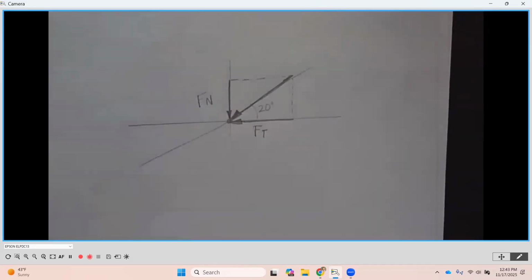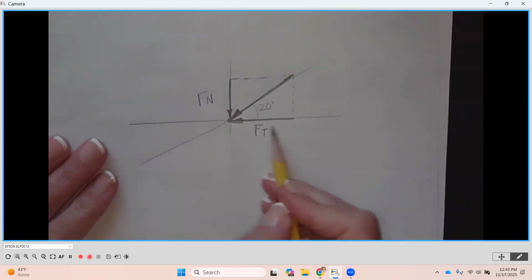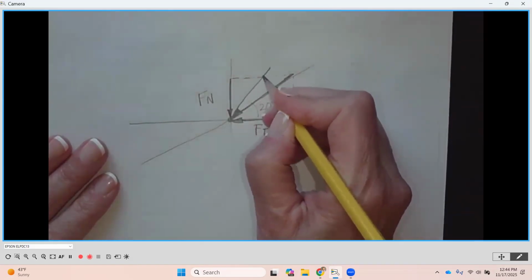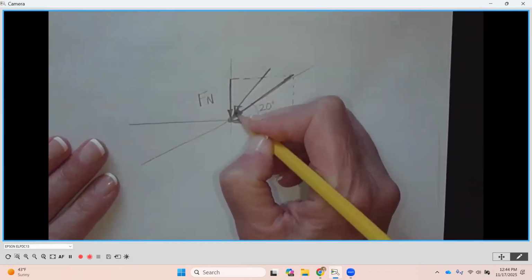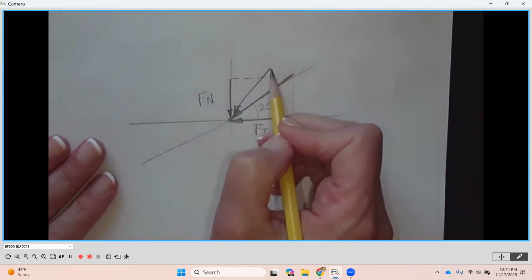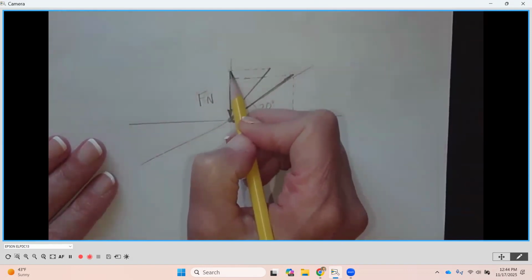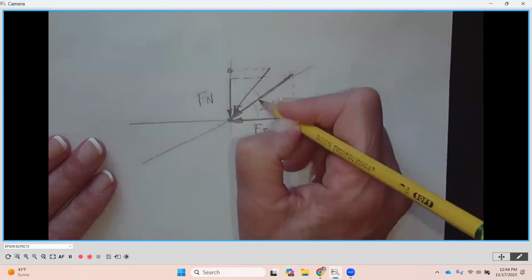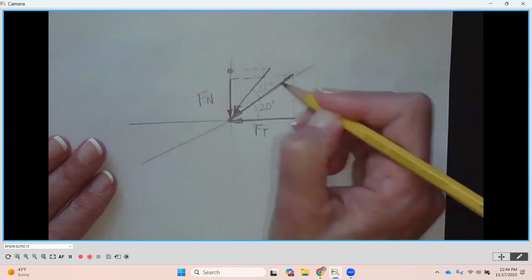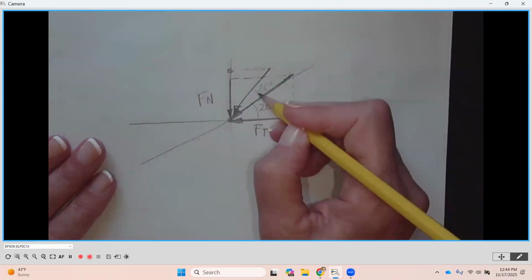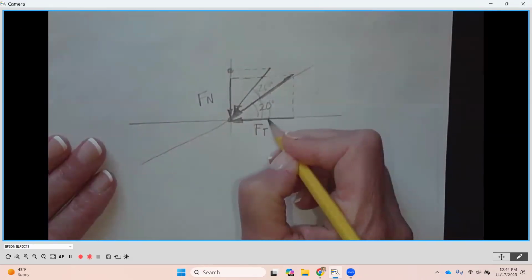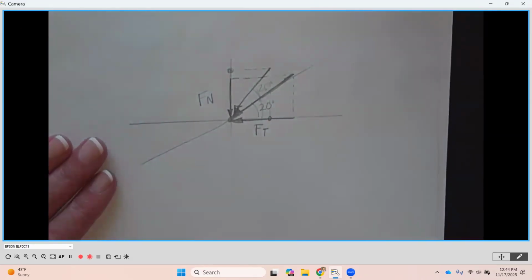Now let's say we move this up to a 25-degree pressure angle. From horizontal, we use that same force. I'm going to exaggerate this, but let's say I do this. I've got now a resultant force coming in here. What happens is my normal force is going to get larger, right? You can see that. So this goes up, 20 to 25 degrees, from horizontal up. But then if I go down here, my tangential gets shorter.